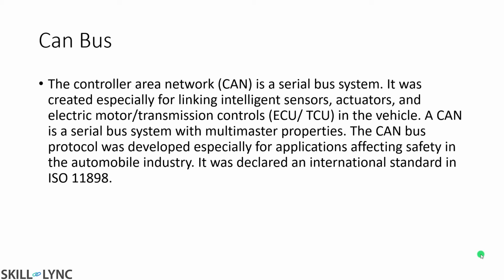A very simple example would be the automatic start or stop in vehicles. All these different inputs go to the ECU, and then the CAN bus will make the decision if all the systems are in. The car is idling, the steering is not moving, then maybe the air conditioning, the engine temperature, and so on. It will make a decision. Okay, the vehicle looks like it's stopped, and the position of the brake and all that. So let's just cut off the engine for now. This is all going to be made by the CAN bus.